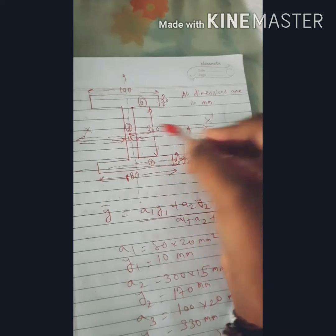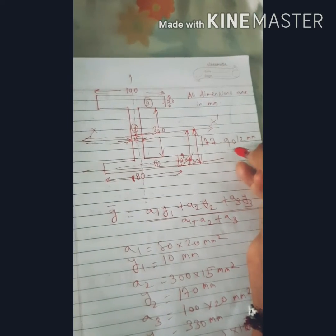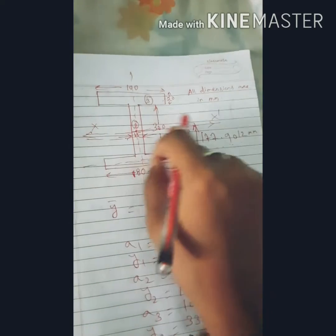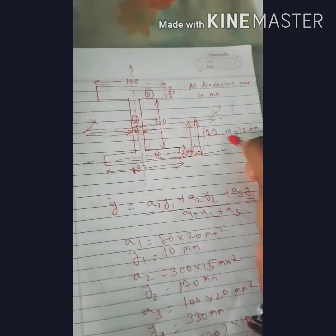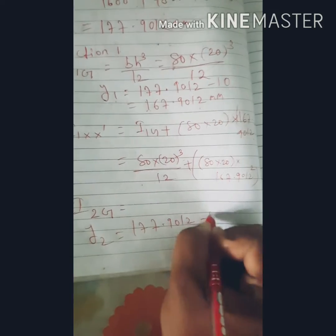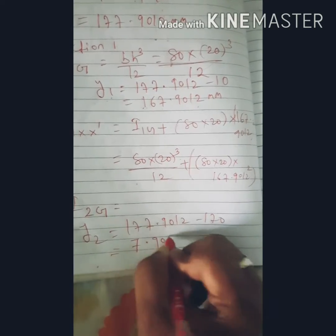But the center of gravity of the whole I section is at 177.9012 mm. So the distance between the two centers of gravity is y2 equals 177.9012 minus 170, that is 7.9012 mm.